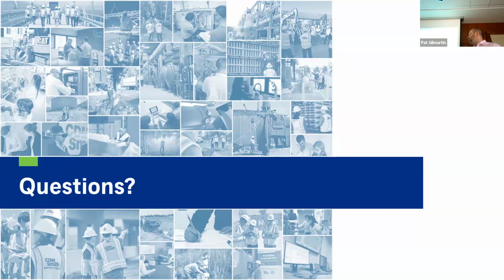Typically for tolerances, we're looking for anywhere from, for the more urban environments, more of a 2 to 3 foot delta. But if you're in the middle of nowhere, you can get up to 5 to 10 feet. So it really depends on the risk associated with the project. For the smaller drills, especially if you're using more regional contractors, they're going to use walkover units whose accuracy may be on the order of a couple feet off, so 2 to 3 feet. And so you're always going to have deviations from that original alignment. Your specifications are really where you have to determine how far off, but they're never going to hit exactly along that alignment that you show.